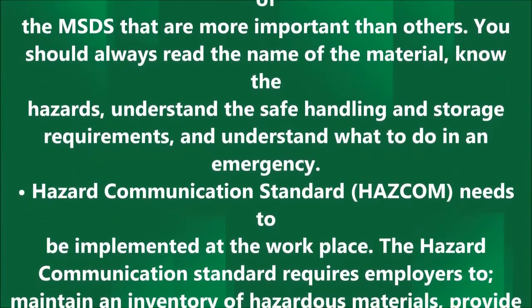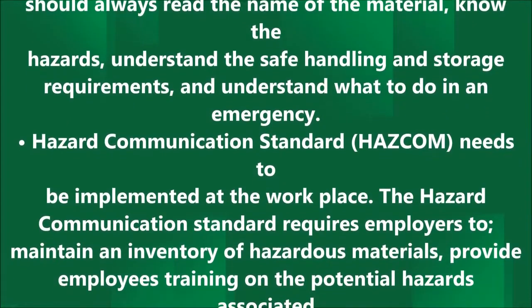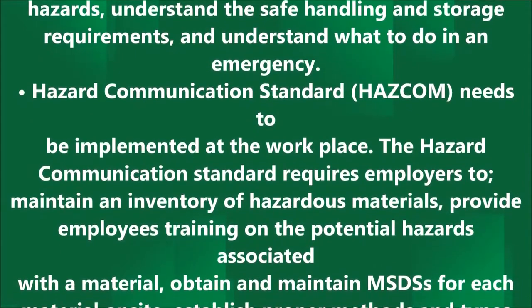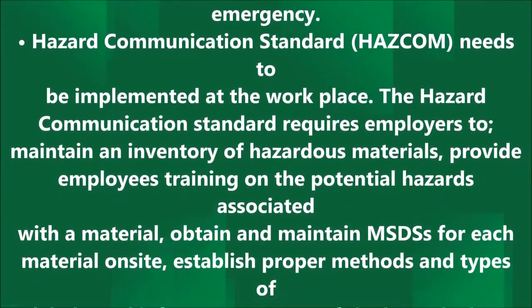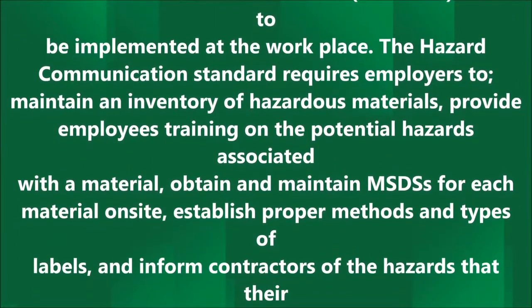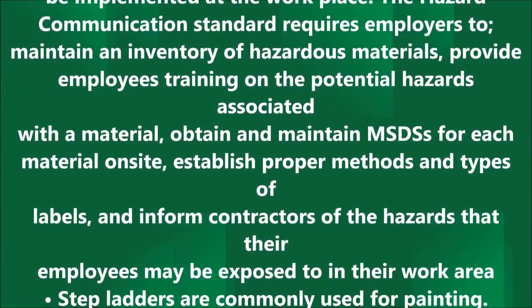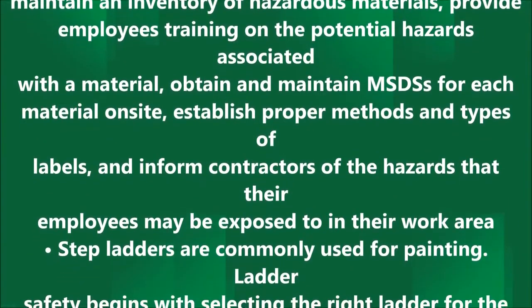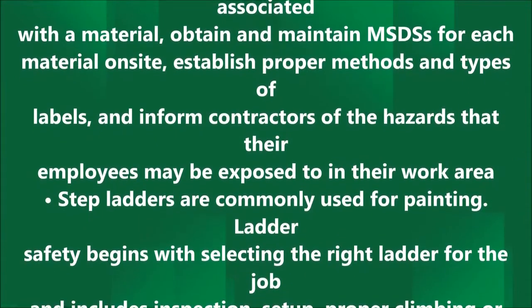Hazard Communication Standard, HAZCOM, needs to be implemented at the workplace. The Hazard Communication Standard requires employers to maintain an inventory of hazardous materials, provide employees training on the potential hazards associated with a material, obtain and maintain MSDSs for each material on site, establish proper methods and types of labels, and inform contractors of the hazards that their employees may be exposed to in their work area.